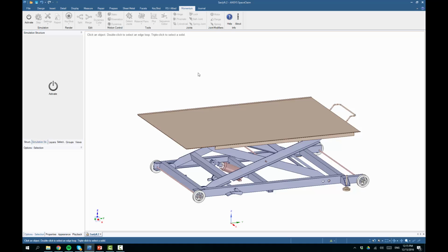And for those of you who are familiar with ANSYS Space Claim, you know that you can import CAD assemblies from virtually all known 3D CAD formats and edit those geometries directly in this environment. And those formats also include step and parasolid files, for example. And you can edit those as well using the direct modeling capabilities of ANSYS Space Claim. So that is really, really powerful in and of itself. And obviously you can create your own geometries as well. But that creates this really nice setting and environment for Algoryx Momentum. So you can modify your geometries, run your simulations, and really get to know your design.